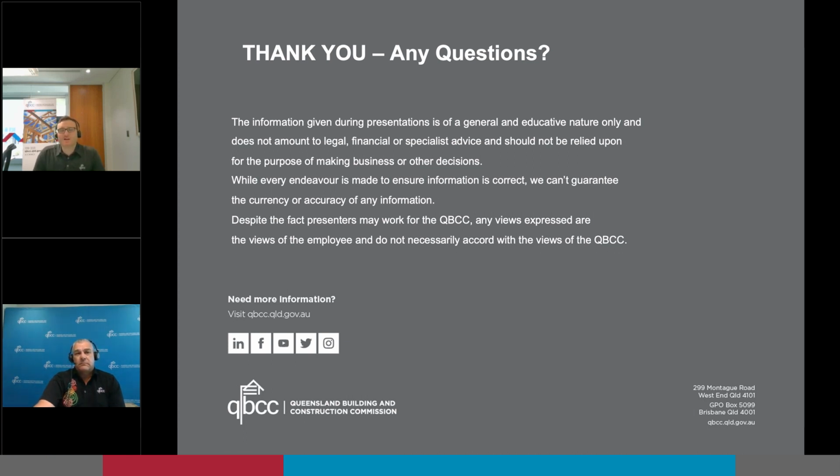Yeah, well, that was the second part to that question. If something is installed incorrectly, is it still a non-conforming building product? If a product is not correctly installed as per the intended use and the relevant installation instructions, remember the plasterboard example, it's not the product's fault. That's something that possibly could be looked at through the defective work process as opposed to an NCBP. One thing we remind you of in the legislation is the required information for correct installation. If something is not installed correctly, that doesn't necessarily make it an NCBP.